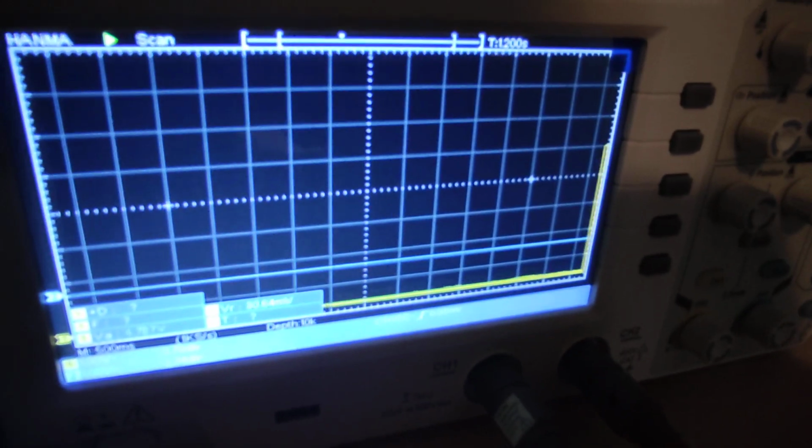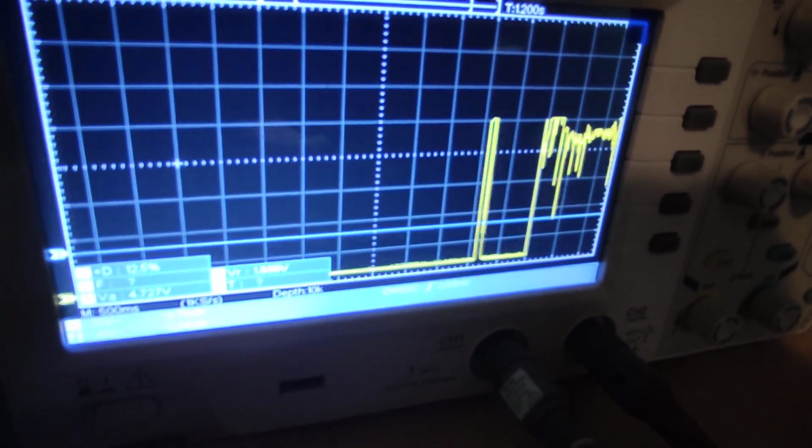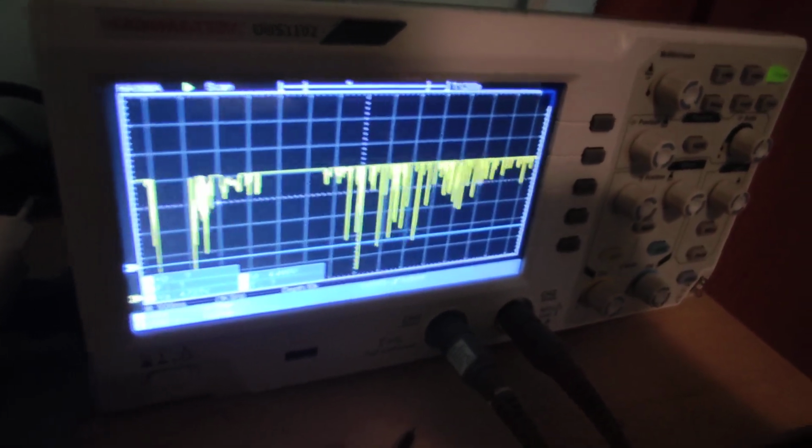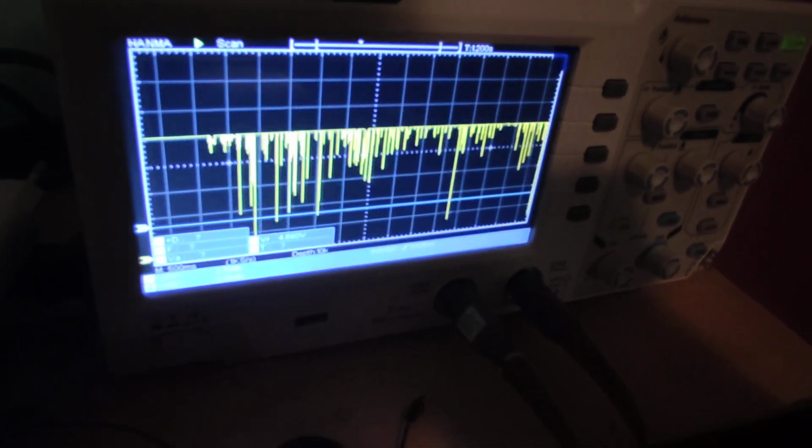Okay, so basically here I connected a button with a pull-up resistor, as I showed you. There is the voltage connected to 5 volts. So whenever I'm pressing the button here, you expect to have 5 volts, and as you can see, there is 5 volts. It is very, very noisy, just because also I'm moving my finger here. If I move my finger, you see that the noise is coming from the contact of the button.